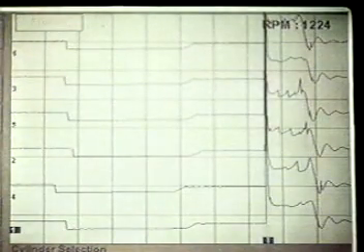So don't make any kind of diagnostic decisions because the points of primary turn-on are not perfectly lined up. We will give you, again, a maximum of 500 microseconds variance. So hopefully we prove to you technicians that this scope check is a 5 or 10 minute job max. So what we basically did, we've done a tune-up verification procedure. We have qualified this car for maintenance tune-up.